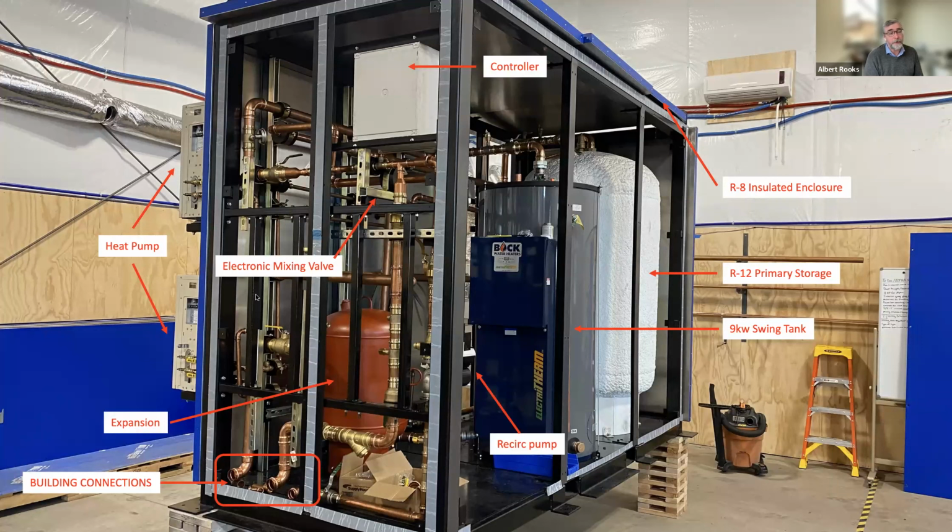And if you're in cold climate, 7, something like that, you can make 150, 160, 170-degree water all day long. And you would be looking for a heat pump that has, maybe, a glycol loop between the heat pump and a heat exchanger in front of the primary storage. That's what I would really do in those climate zones. That way, you lose a little bit in COP because you've got the heat exchanger in the middle, but it allows you to work in much colder climates.